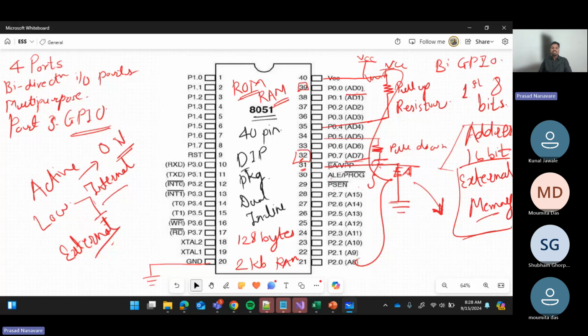there is always noise in electrical and electronic signals. So any higher signal could be noise also. It is easier to detect the dips in the voltage than the ups. Ups could be the noise also, but with a dip, voltage stays constant at 0 on the port, so that is easy to detect. So that is why active low has come into play.